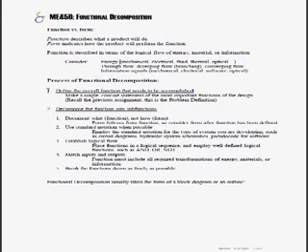And the two main steps here that the worksheet walks you through is, first of all, defining the overall function that needs to be accomplished, whether that's a nail gun or whether that's a coffee maker. Be very clear about what this is doing, or else you're not able to decompose a system, because you don't have a system that really exists. Then you can decompose the function into subfunctions. You're documenting what happens, not how to do it.